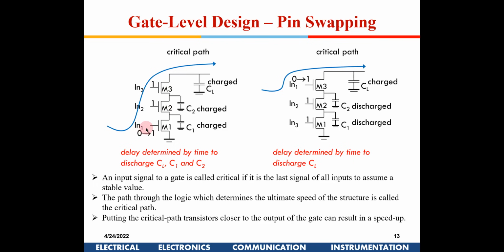So in this case, if you see the output node, when all the 3 inputs are 1, for a NAND gate, what happens? What is the thing which has happened to the NAND gate? When all the inputs are 1, the output has to go to 0.